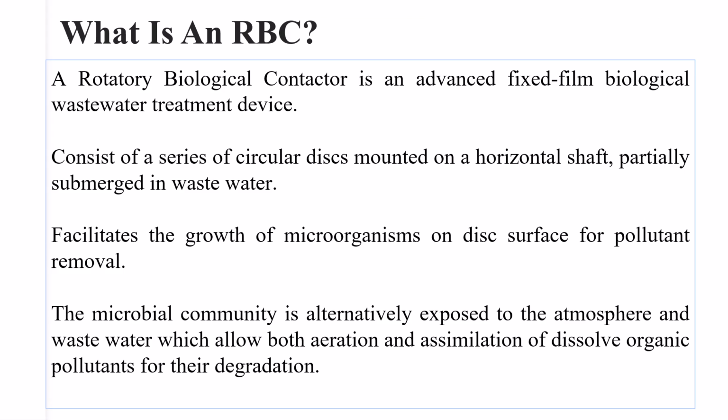Now we will see what a rotary biological contactor is. It is an advanced fixed-film biological wastewater treatment device, and it consists of a series of circular discs mounted on a horizontal shaft, partially submerged in wastewater. This facilitates the growth of microorganisms on the surface for pollutant removal. The active microbial community is alternately exposed to the atmosphere and wastewater, which allows both aeration and assimilation of dissolved organic pollutants for their degradation.